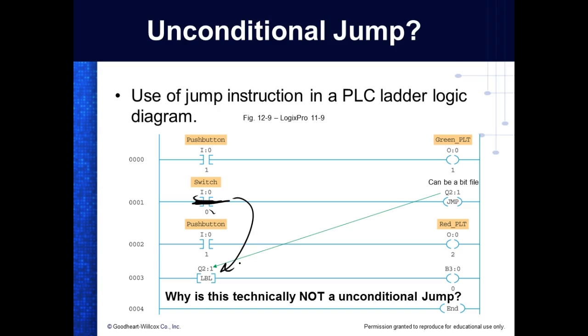So here what they use is the B3:0/0, right? Everybody understand that? So you can't have an input instruction on the left without having something on the right. You've got to have an output instruction for every input, at least one.